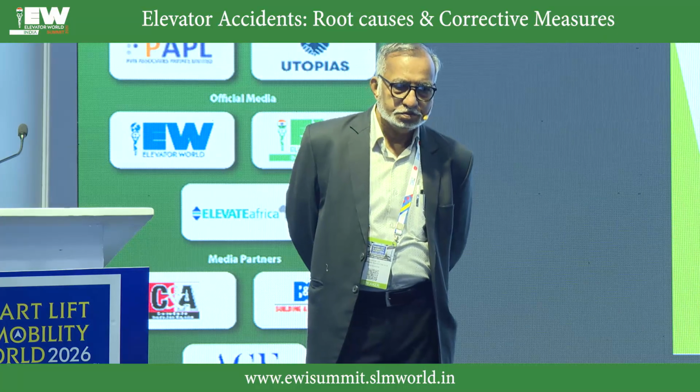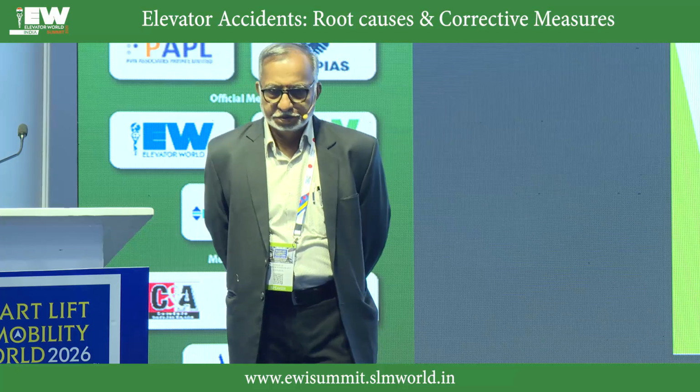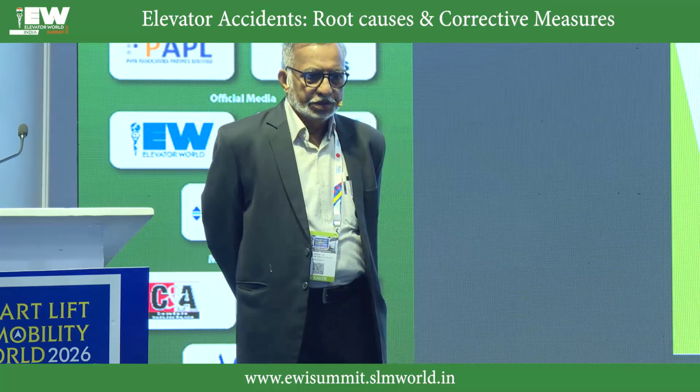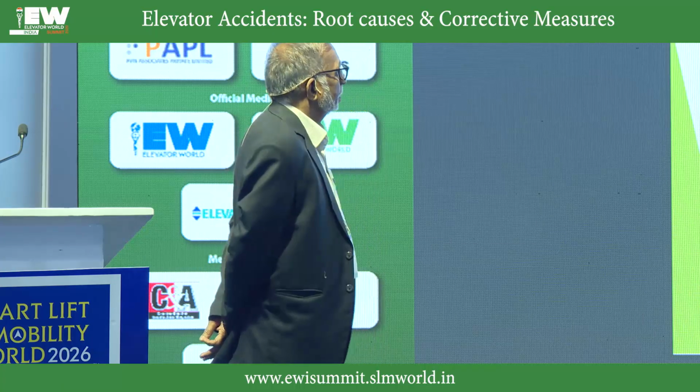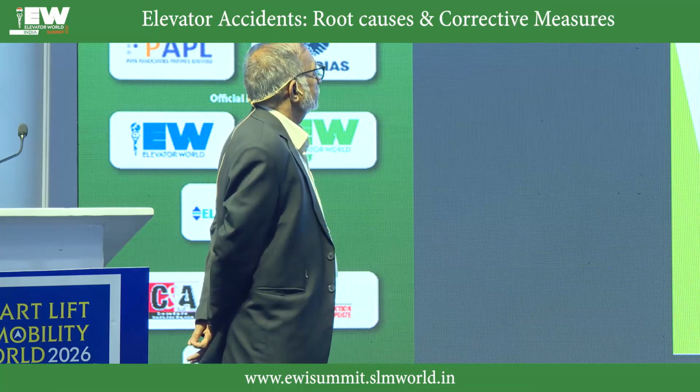Injuries during door closing. Now the reason could be that the door sensor is not working or control failure. Lock setting is not proper, leading to a larger gap between the door panel and the ground bottom level. So these are the reasons for the failure or cause of the accident.